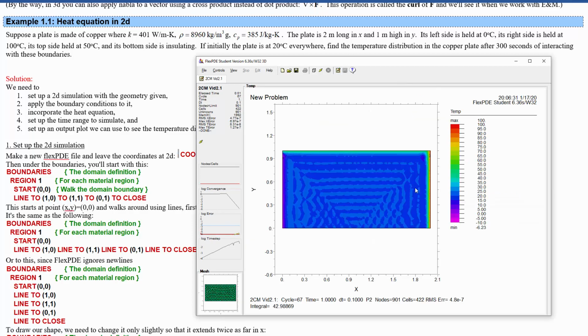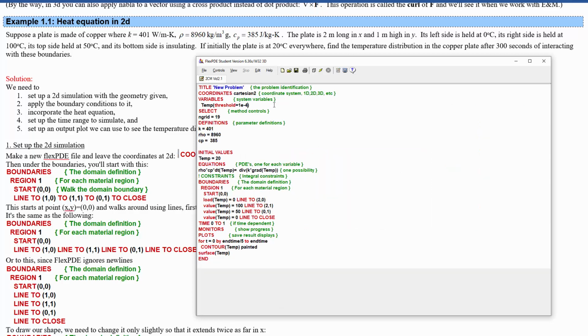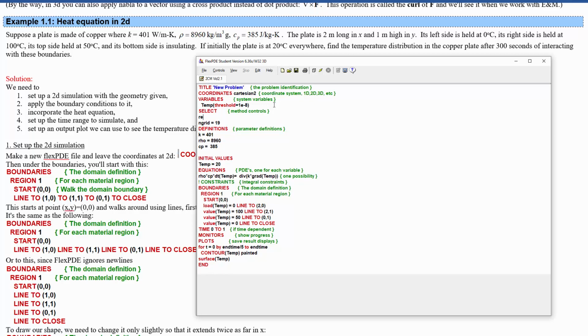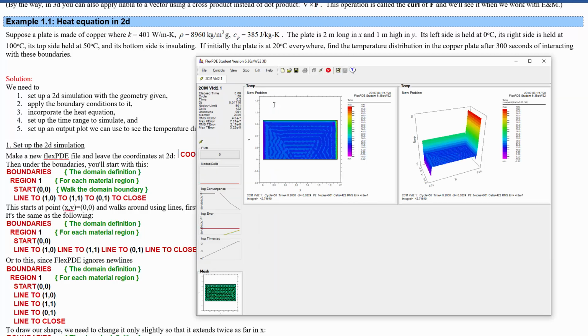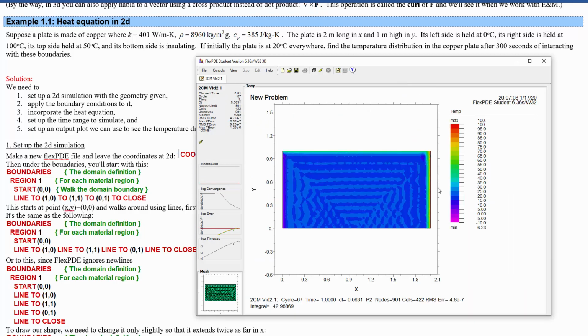Okay, so now things are working out a little bit better. We do still have some phenomenon where changing things immediately in temperature has led to this local point drops as the finite element method doesn't resolve things totally well. But those areas have taken up less space here than before. Another thing we can do to try and fix it is make the threshold smaller and add in a lower error limit. But they have no effect.